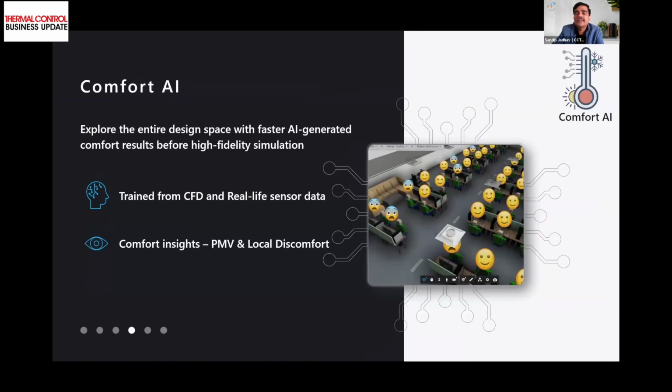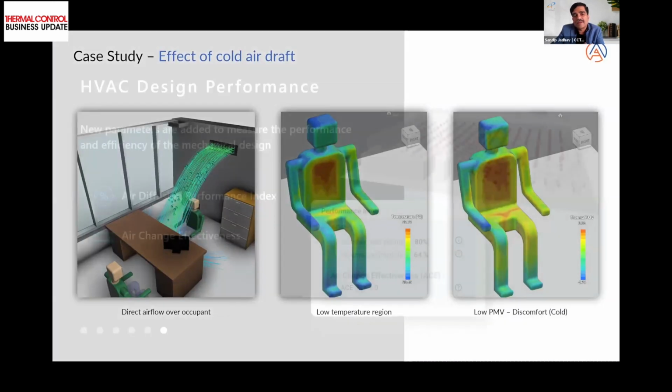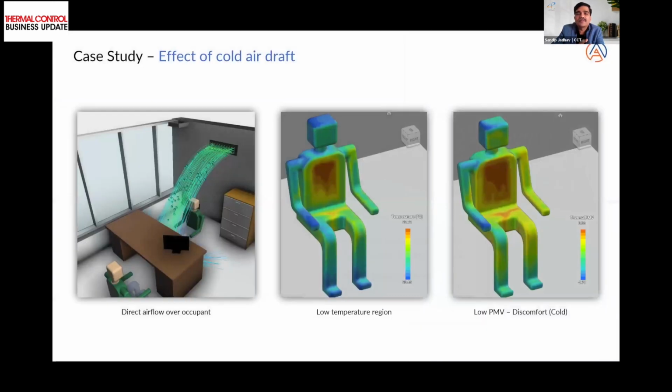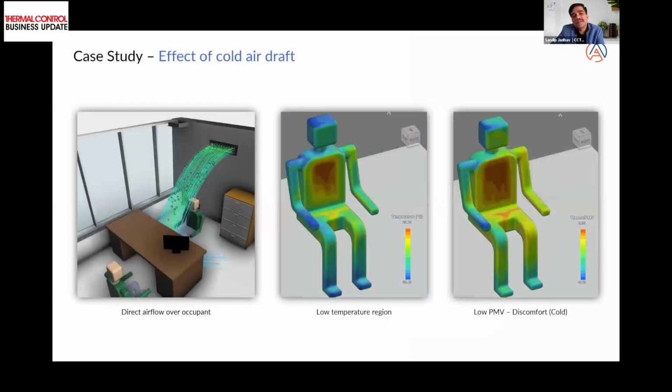And then we have also built an AI tool to do a very quick evaluation of comfort, because when we want to make some changes, it will quickly run and show you results before you do an actual simulation. And then we bring up other parameters such as the ADPI parameter and the AEC parameter, which are helpful for evaluating how good your ADPI design is.